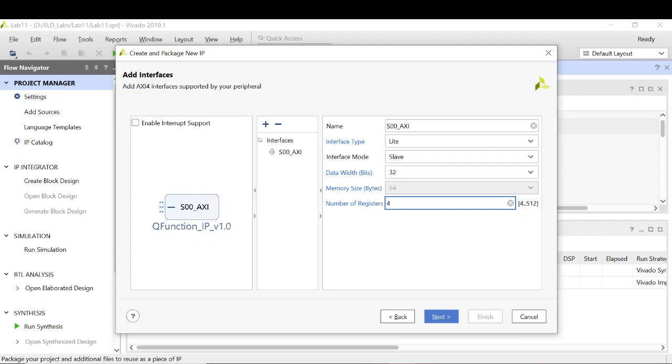So there is this C code and then there is this IP, which is implemented on the hardware. That is the PL part of your design. In order to communicate with the IP, you can communicate through these slave registers. You will write to these registers and you will read from these registers. So there are read and write transactions going on between the IP and the C code.